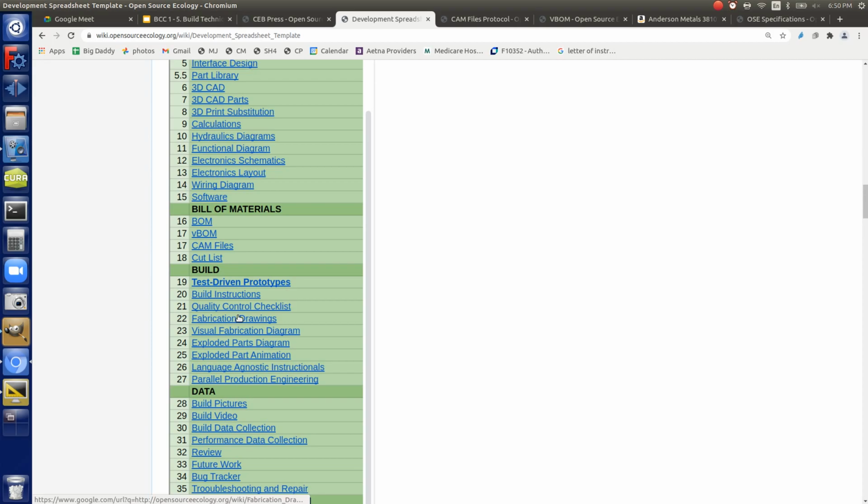Fabrication drawings. Those are the dimensional drawings, and there's a particular way you do them. You want to organize them in a way where you have X, Y, Z views, like the front view, the top view, and a side view. You can't go wrong with it. I know in some of ours we just had one view, then some other angle view, and you couldn't really relate it.